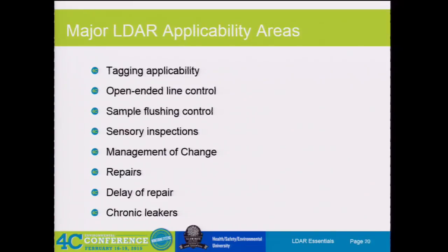Good. So make sure when you guys do it, some of the sites I've been at recently actually have another question added to their out of service points of making sure that, okay, is this LDAR out of service? Did you purge this? Or do I still need to keep it in my route just because you say it's out of service, it's not out of LDAR service? So that's a good piece to add in.